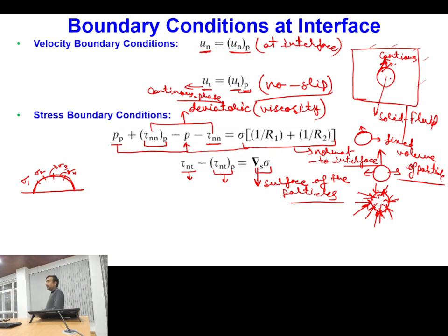So it means that at low temperature the surface tension coefficient is high, and as we increase the temperature of the liquid, the value of the surface tension coefficient decreases. Particularly at the critical point, after the critical point the entire liquid will be in the vapor phase. So the value at the critical point is 0, and above that of course it will be 0.